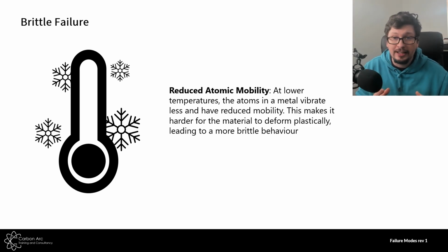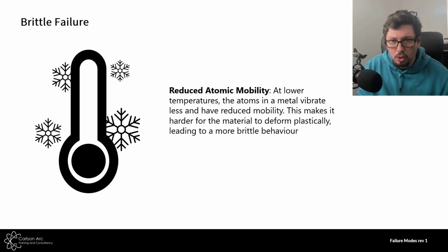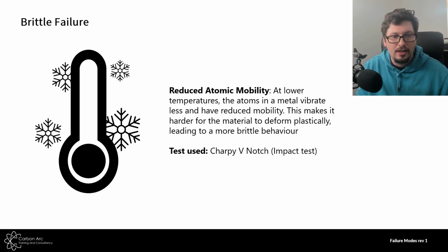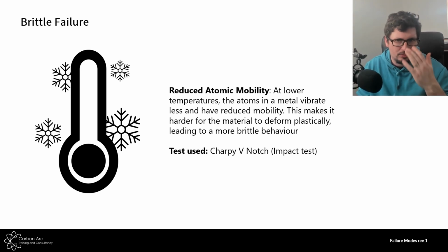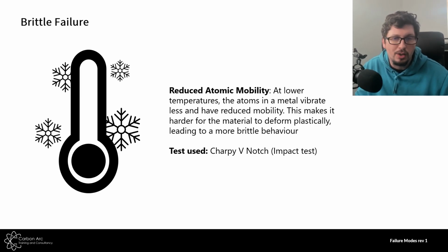So brittle failure is always at a low temperature. So if you're looking at any multi-choice questions or anything like that, and it's referring to low temperature, 99% of the time, it's going to be talking about brittle failure within the structure. Okay. Now, the most common test for detecting the susceptibility to brittle failure is a Charpy V-notch or an impact test. Okay, very common test, which we talk about in other videos. So please go and give them a watch.